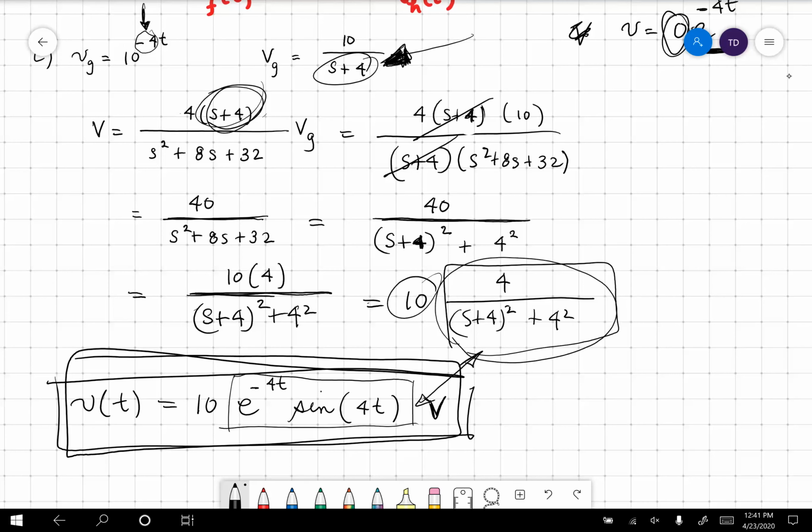So there's only one thing that we haven't seen happen with this circuit. And that is what happens when a term from the input has a denominator term that matches a denominator term of the circuit. And we know that that is going to be excitation at a natural frequency. And so that is where those repeated roots that we have to expand in our partial fraction expansion tell us that we excited the circuit, for example, at this input frequency, but that was already a natural frequency. So the output, the forced output, remember we had to put a t multiplier in our guess, like that.